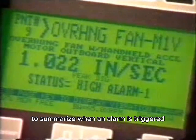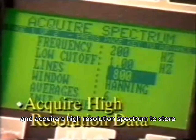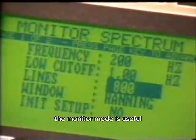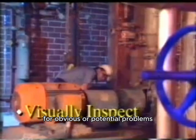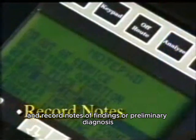To summarize, when an alarm is triggered, verify that the data looks accurate and acquire a high-resolution spectrum to store with the point. The monitor mode is useful to check other parts of the machine. Be sure to visually inspect the machine for obvious or potential problems and record notes of findings or preliminary diagnosis.